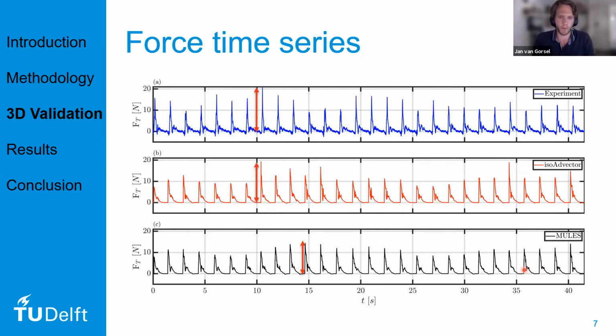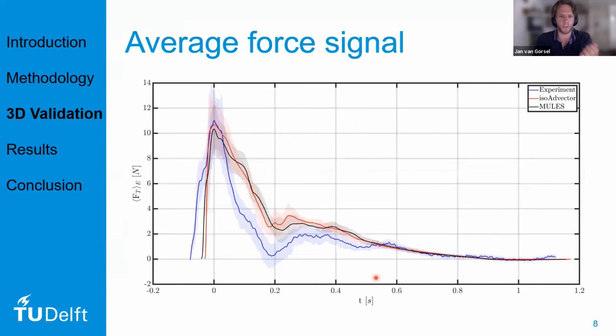The second interesting thing to see is a returning long wave in the domain, which is approximately 20 to 25 seconds, and this corresponds with the eigenvalue of the waveform. Furthermore, as we have regular waves, we can take the individual force signals from the time series and average them out, which results in an ensemble average of the force signal.